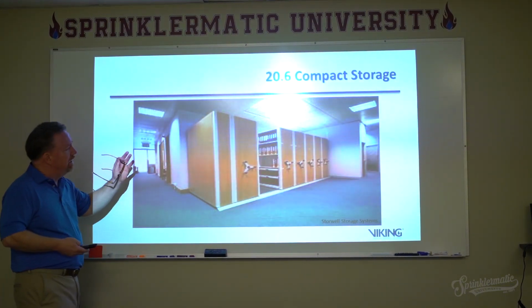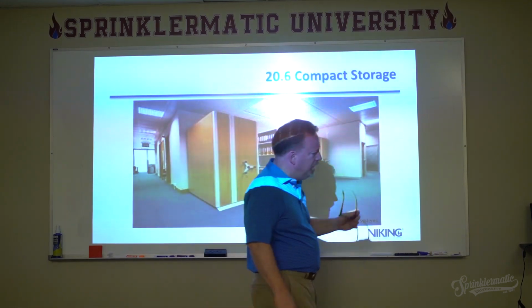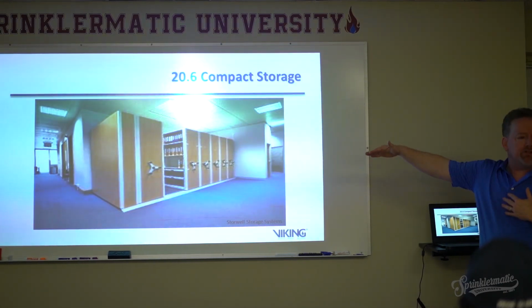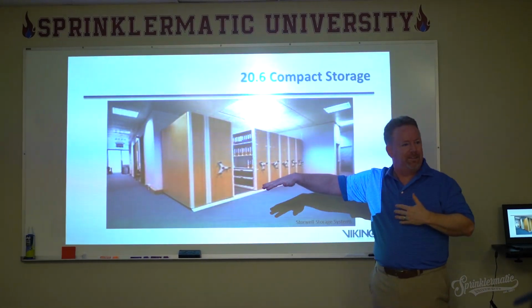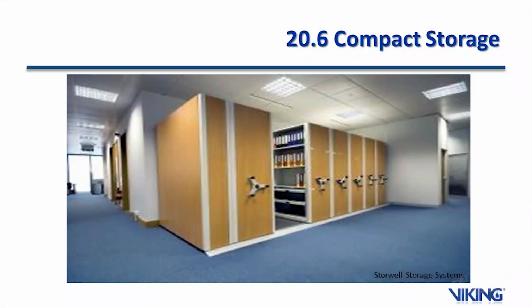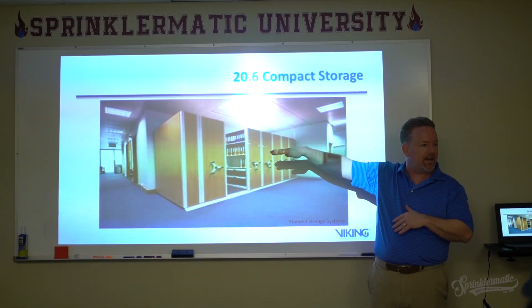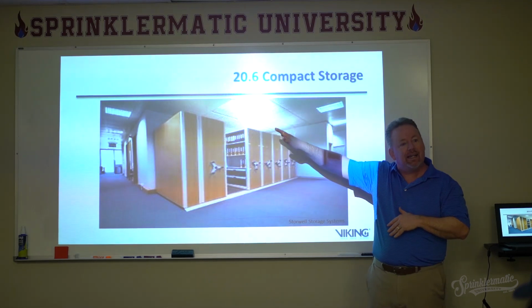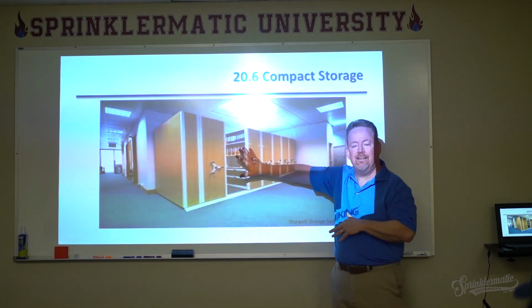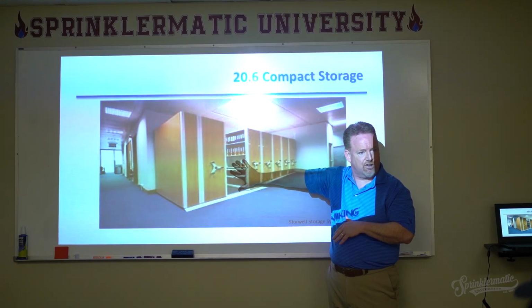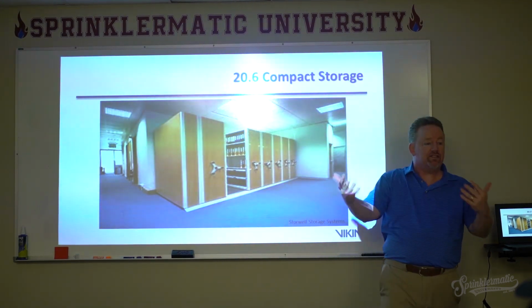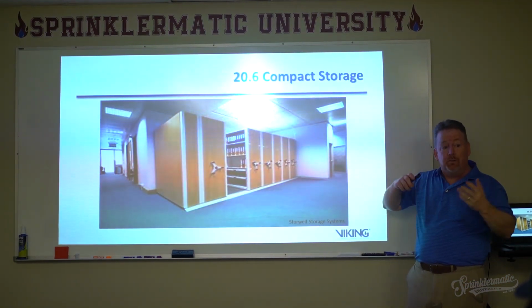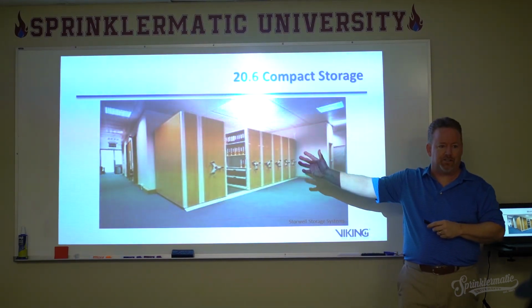Finally, we'll finish with compact storage. This was an interesting one mainly because with compact storage, what they were trying to do was not call it storage at all. They were saying, look, these go up to a certain height, but they're always in a light hazard occupancy. They're always in a doctor's office or a lawyer's office or something like that. So the question was, can we protect the storage in here with simply a light hazard occupancy approach? And sure enough, we looked at this and said, well, man, there's a lot of fuel in there. That's going to burn really well.